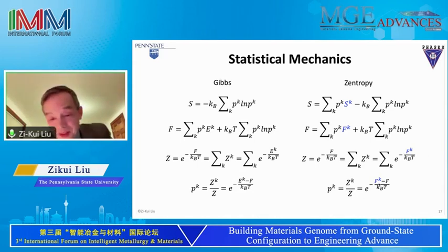This is very significant, because when you change the two variables, your probability is different, right? That means the whole temperature dependence is different. Your free energy is different. Okay, that's very dramatic. That's why DFT alone for the ground state is not enough, because you get the wrong free energy. That's why when we do CALPHAD calculations, we always find that we have to adjust the parameters, the energy predicted from DFT, in order to fit to experiment. The reason is that it misses one part of the entropy, and the free energy is incorrect.